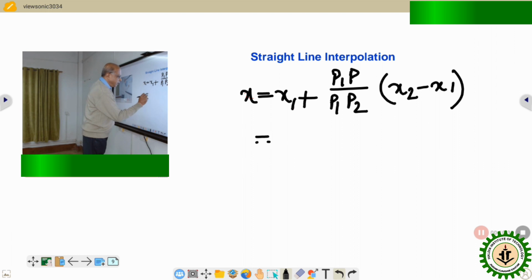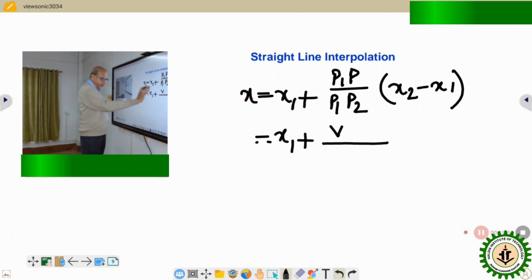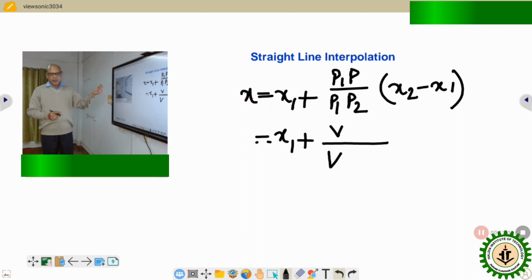Now eventually it is expected that the tool will have a definite velocity along the same path. So this distance, in the absence of any acceleration or deceleration, can be represented as v multiplied by t. For the time being, I am omitting the t part. Similarly for P1P2, velocity remains the same. Now just consider that P is not a static point. P keeps on changing dynamically in real time. Its starting point is P1 and eventually P will reach the destination P2 as far as x-axis movement is concerned. Now one pulse will be emitted to cause some incremental distance along the x-axis.